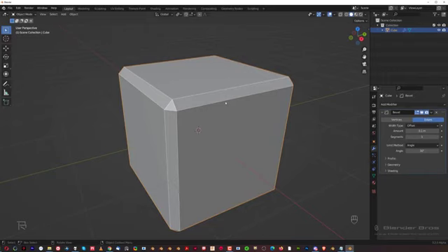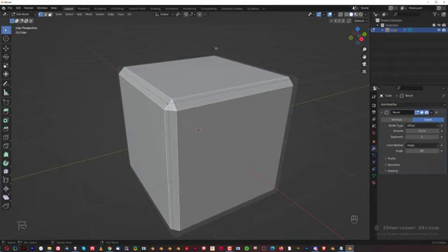And if I click on that cube here and go to edit mode, you can see that the outline of that cube doesn't really get beveled. The reason for that is that this bevel here is live, so the modifier is active, meaning that bevel is actually a fake, an illusion. It's not real geometry yet.